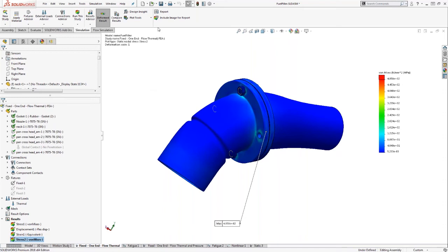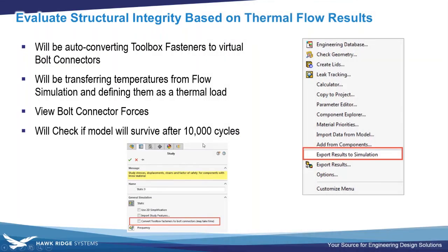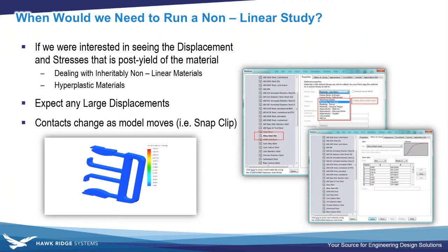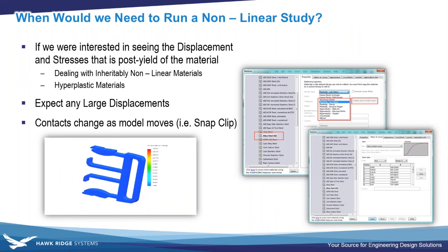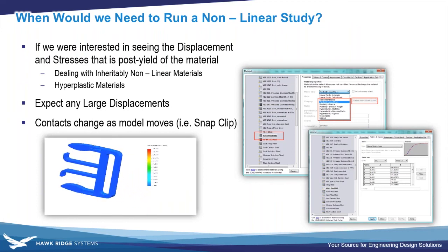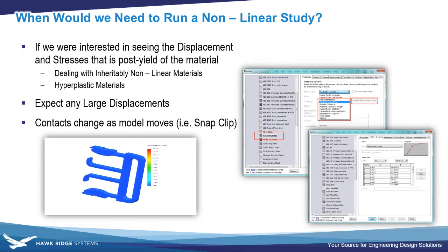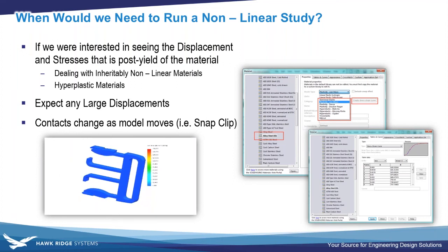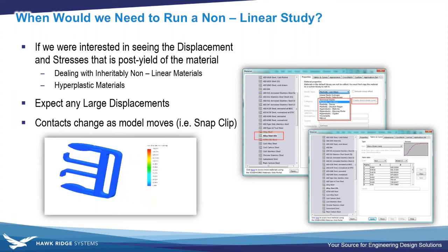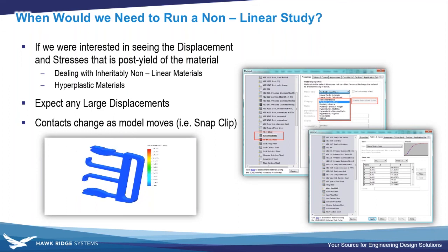The next thing that I want to show you is, right now we're just looking at a linear static analysis, but there may be a situation where we actually need to run a nonlinear analysis, and it's always been the question of, when do I run one versus the other? Well, it's always a good starting point to see whether your study is going to work in a linear static analysis, a very simplistic study with those assumptions, right? The assumptions of a linear static are just small deformations, loads being applied slowly and gradually, where we don't have control of the time step here.